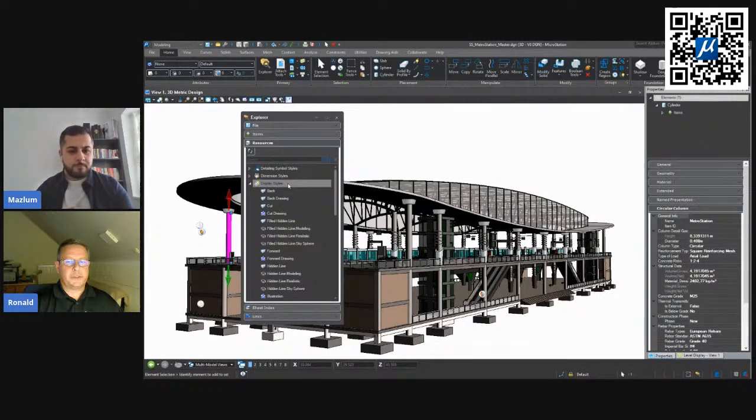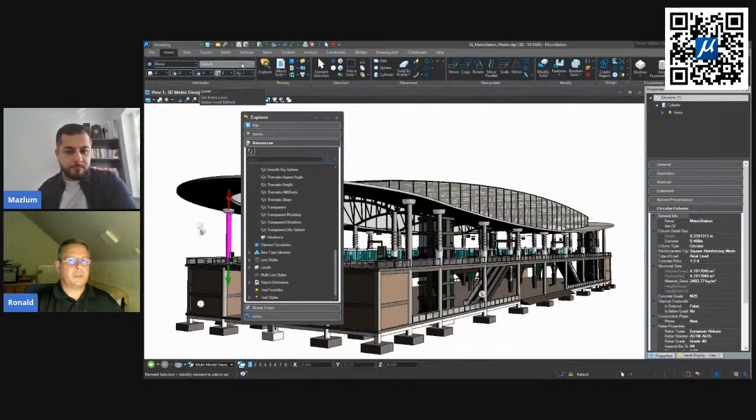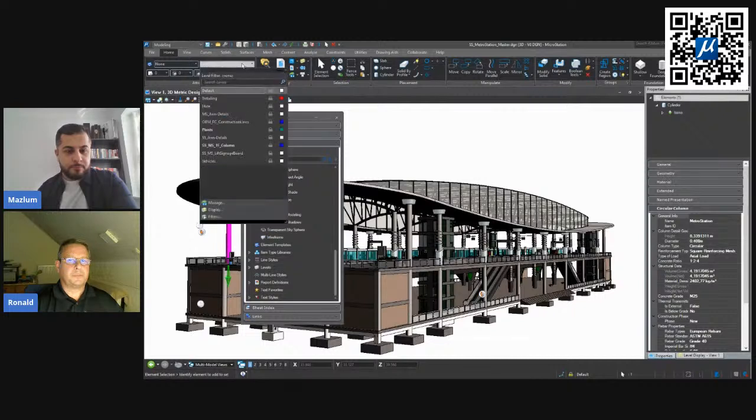Then everybody is using this and is attached to the settings. So a CAD administrator has to update only one set of files, and everybody else will get the updated files. And if you add, for example, some new levels or layers in these libraries, then they will be available the next time you open a file. Every time you open a new file or an existing file, you get the libraries included, and you will see the new levels right here in the level list.